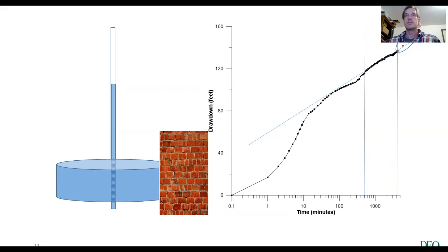It's drawing down at a much faster rate all of a sudden. Well, that's a clue that it has hit a boundary condition somewhere in the system, meaning that it has stopped looking out in some portion of the aquifer system. It can't find water, it can't expand out any further, so it stresses the part it can already access even harder and causes drawdown to occur. And that's a very important clue to folks that are analyzing these and are responsible for trying to describe these